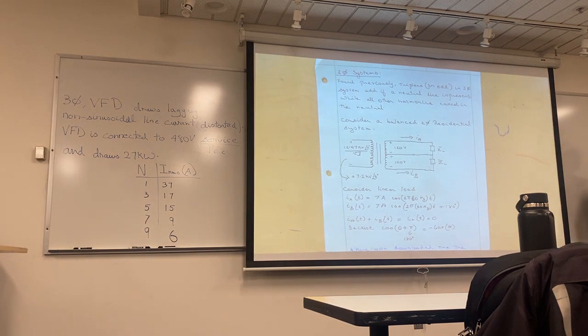you have 3 lines going next to your house, not the big ones, but the ones on which you see a lot of birds, not the ones way down where no one actually gets. I'm just going to make this up as A, B, C. Between any two phases, you will get 12.47 kV. Goes without saying that if I put a multimeter between A and C, I'll get 12.47 kV.